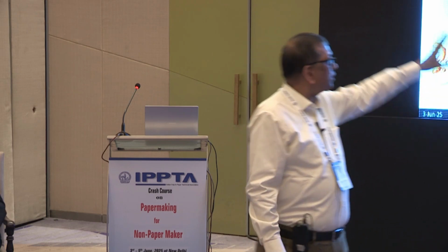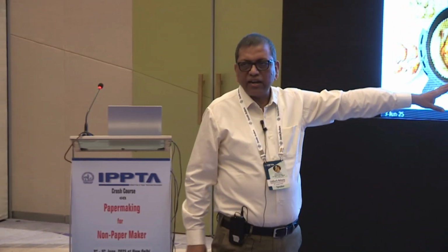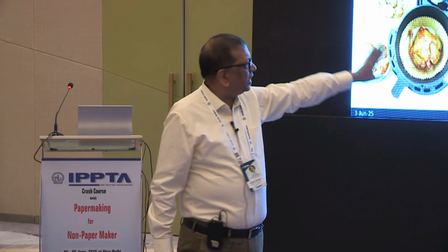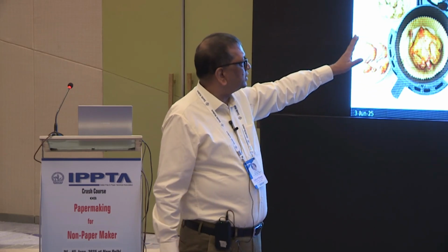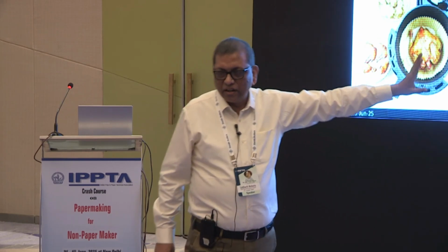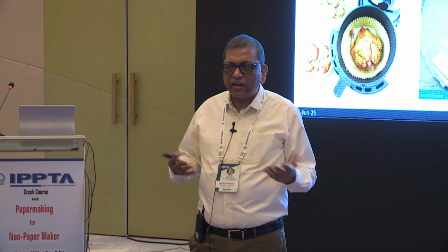We can't use, suppose someone says that I put up a machine, I wanted to make parchment paper, and the CTQ of the parchment paper making, if I put the CTQ, is a high tensile, low Gurley porosity, good dispersion of cellulose during the parchmentation. That is very subjective. So you will get a high tensile, you will get a low Gurley. But when you go for the parchment, because the fiber compositions are different, it will fail.